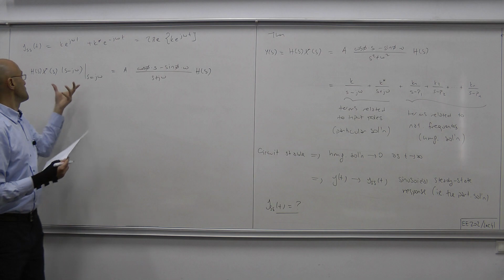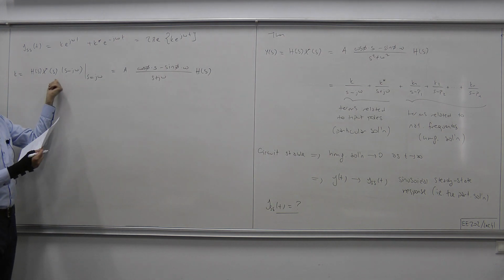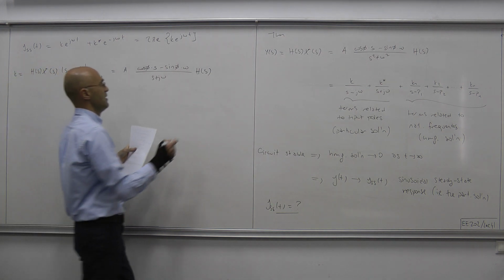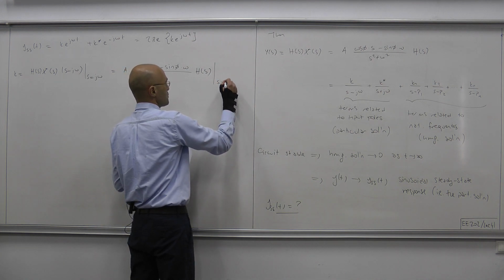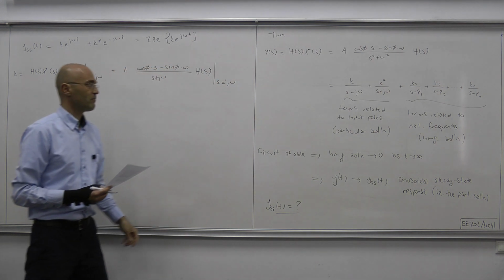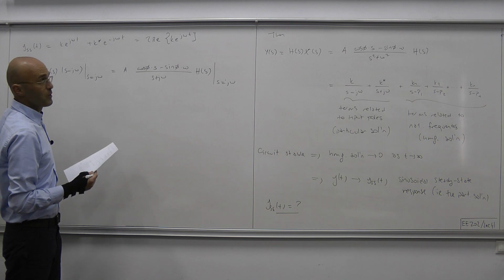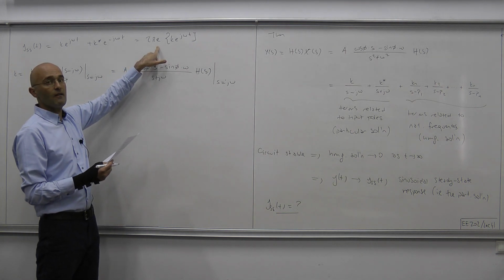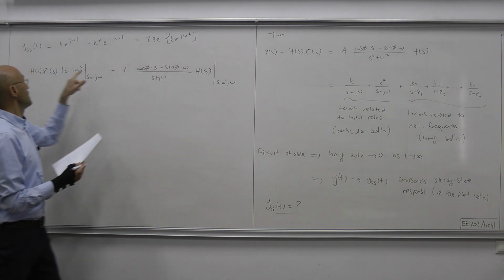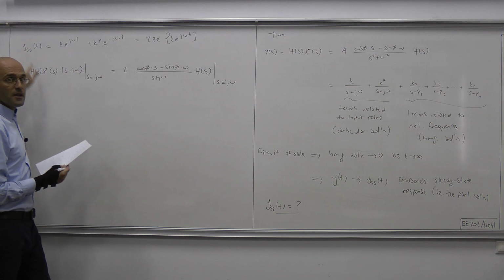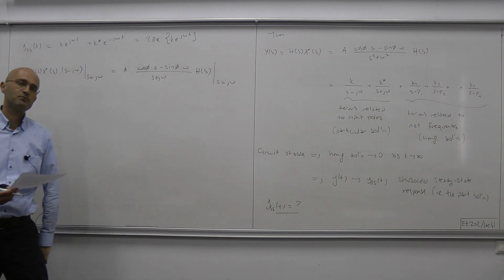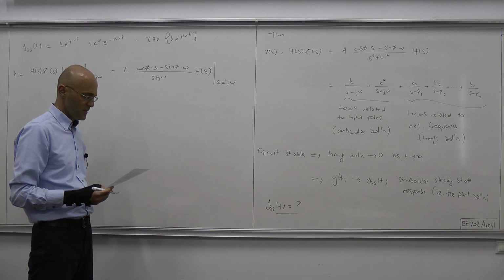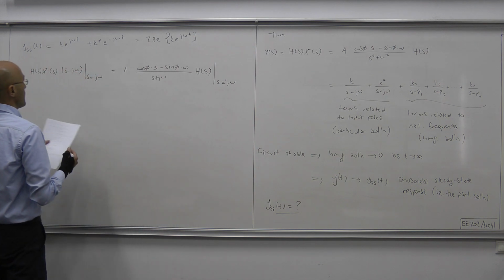Okay, so this is this product Y(s) times s minus j omega, and then we're evaluating this at s equals j omega, and that will give us k. And once we have k, through this relation we easily obtain the steady state or the sinusoidal steady state solution YSST.